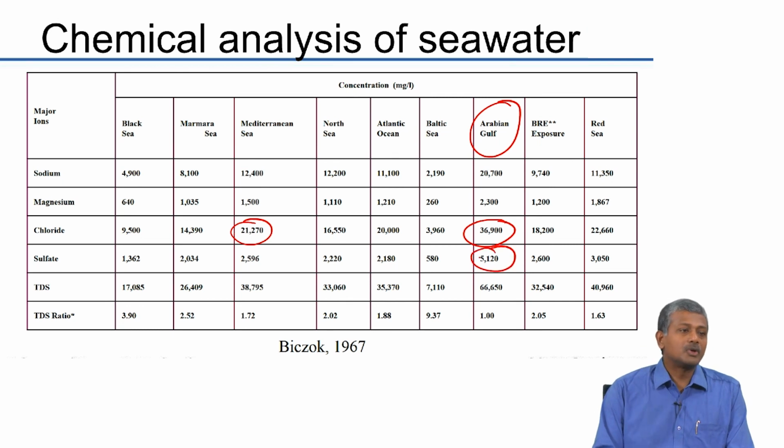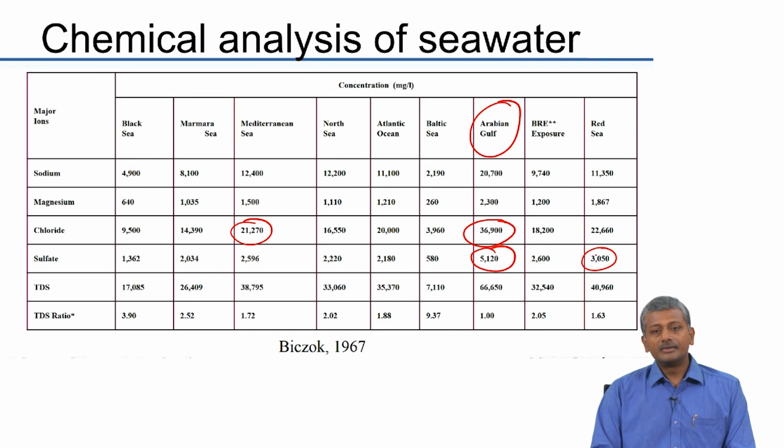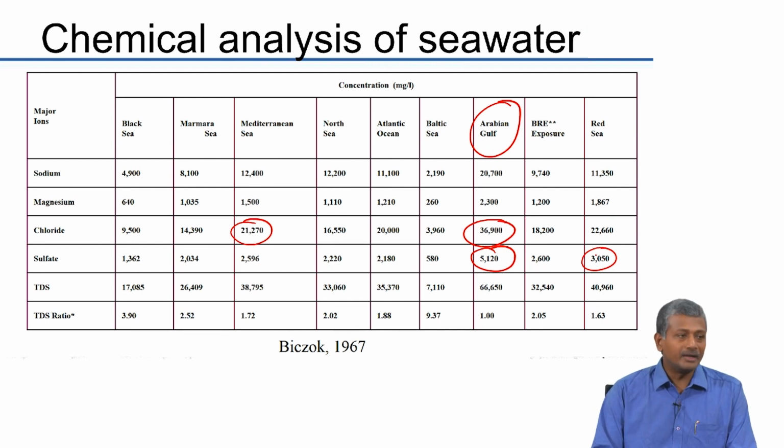Okay. You can reduce the conditions of expansion related deterioration because ettringite formation at moderately lower pHs will not lead to the same kind of expansion as ettringite formation at very high pH. Okay. So, having a supplementary material will help in that instance. Further, using a supplementary material will also reduce the gypsum formation in the system due to sulfate attack, but at the same time as far as chloride attack is concerned, most mineral admixtures also tend to have reactive alumina present in these materials, and the reactive alumina tends to further add to the chloride binding.